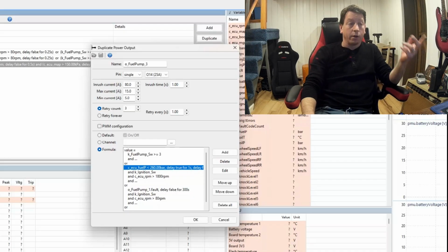I've also had that happen. If I make sure that I define my fuel injector or add fuel pressure compensation, which Link has automatically as a checkbox, my ECU will automatically add the extra fuel if I see a drop versus my base fuel pressure. This is why you should run a fuel pressure sensor. This is why you should tune based off of it.